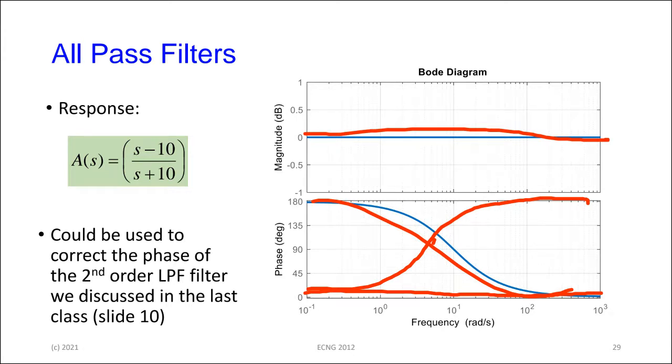Right? Lots of talking, but basically that brings us to the end of our topic on active filters. We did the 4 categories, which were the low pass, the high pass, the band pass, and the band reject filters. We did the first and second order in both the low pass and the high pass. In the case of the second order filters, we created second order filters using the single op amp approach, which was the Sallen-Key technique.